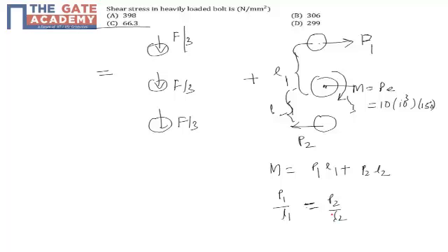It's a simple model which assumes this. It's a simple eccentric procedure which helps in finding out the load caused by the moment. For any number of bolts, these are the basic set of equations used to calculate the shear load due to moment. Now in this problem, L1 is 50 mm and L2 is also 50 mm, so it means that P1 and P2 are equal.